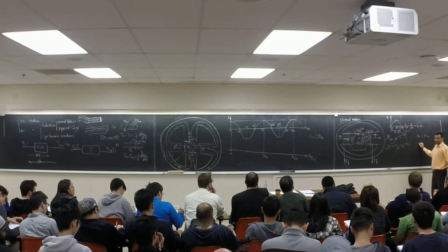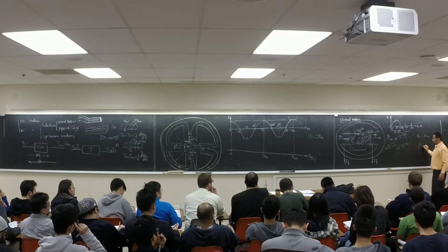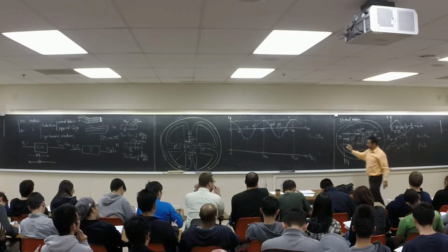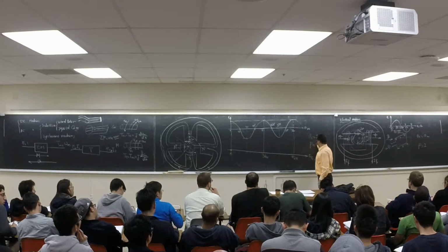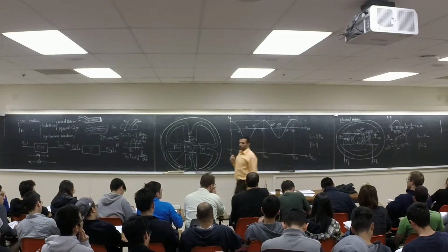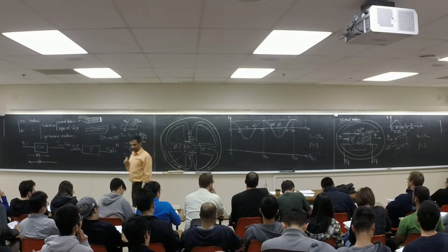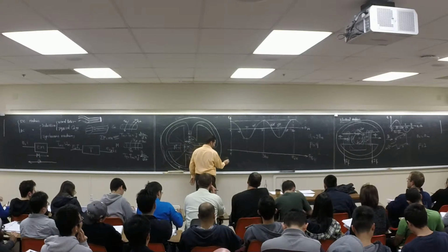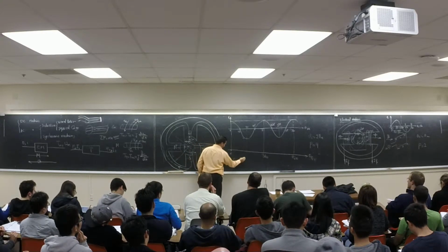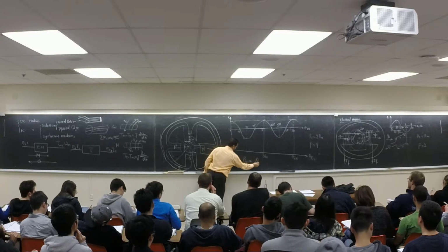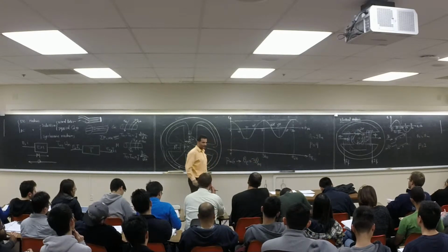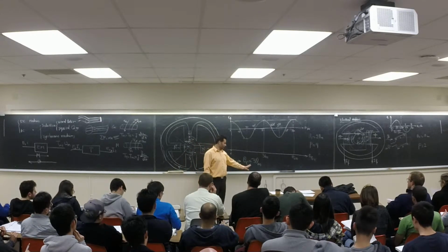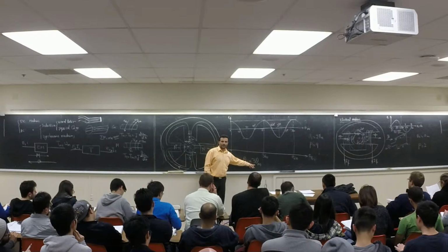Now I'm going to put something here. P is the number of poles. How many poles do I have here? 2. Come here. See, I have 2. How many poles do I have here? 4. Now, tell me I have 6 poles. What's going to happen? If I have P equals 6, what is the relation between theta E and theta M? Right? So what's the equation? Theta E is equal to P over 2 times theta M, right?